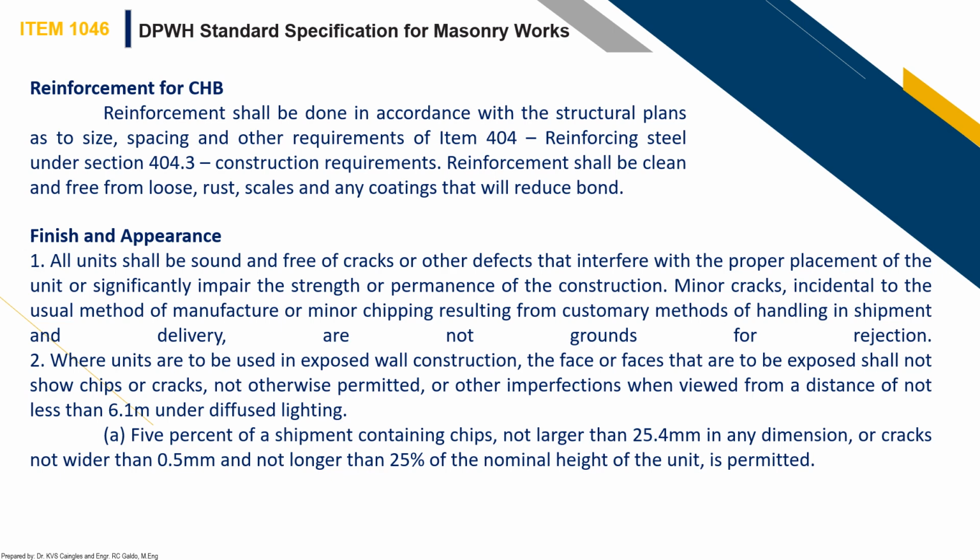Okay? And also, napuntay provisions as to the reinforcement for your CHB. Okay, reinforcement shall be done in accordance with the structural plans as to size, spacing, and other requirements of item 404 or your reinforcing steel under section 404.3 construction requirements. Reinforcement shall be clean and free from loose rust, scales, and any coatings that will reduce bond.